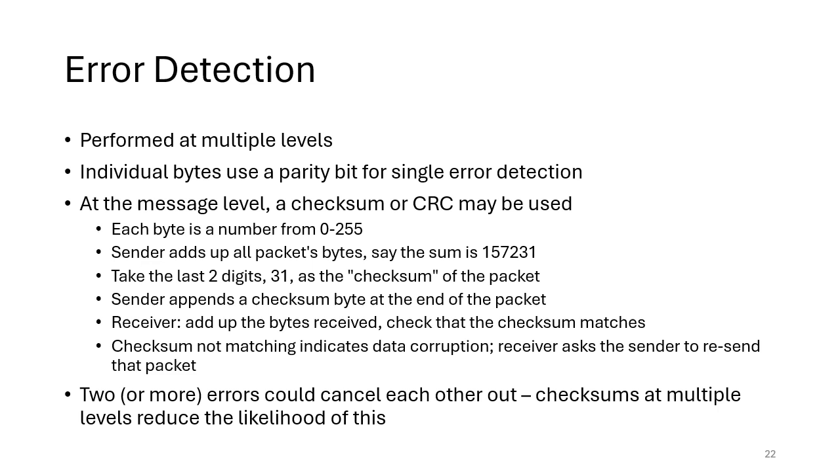Again, the error detection is normally handled at the protocol level. It's not normally something the user needs to worry about, but on some variable networks, again, you can look at those error counters, or you could use Wireshark, and that might determine if you've maybe got a dodgy segment on your network. Maybe there's something that's at the limit of its distance, maybe you're getting a lot of electrical noise, and if you do get very high levels of resending or high levels of errors being detected, that could indicate a problem with that part of the network or with a particular device. So this is useful, but normally in modern applications, you get a human readable message telling you what's going on, rather than have to go down to a really low level to diagnose this.